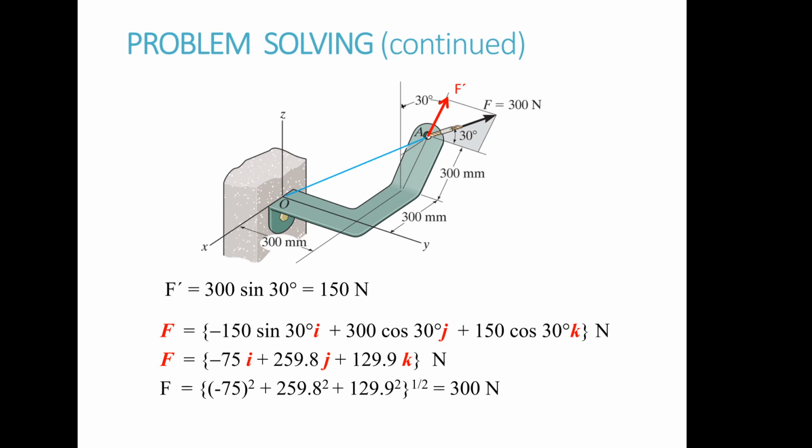So the z component is going to be based on the angle between these two vectors. The z component would be essentially straight up. If you drew this straight down, you would find that it's this right here, right? That angle is the 30 degrees. So you break it up into its x and z components first, how much is going in the x direction and how much in the z direction, because this is right along that plane of x and z. Here's your x component, and it's in the negative direction in x. It's going off in the back, and then it's going up. So here's my z component.